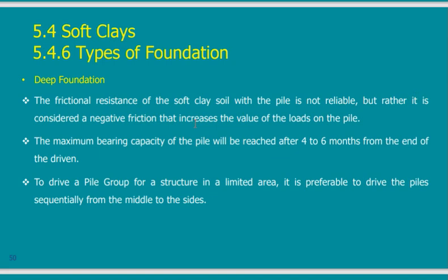So take care in case of using deep foundations that the portion of the pile that is penetrating this soft soil is adding to your problems, not solving your problems. It is not carrying your pile, but to the contrary, with time it will consolidate and it will induce additional loads on your pile. So you have to take it into consideration.